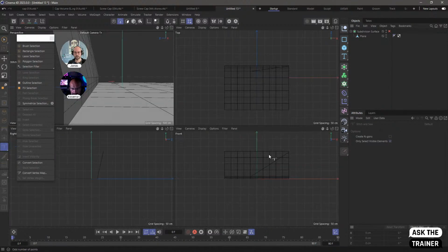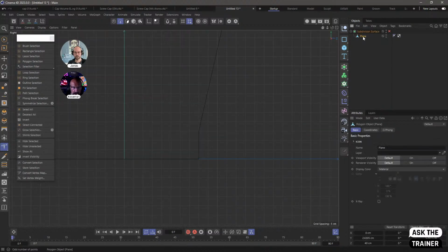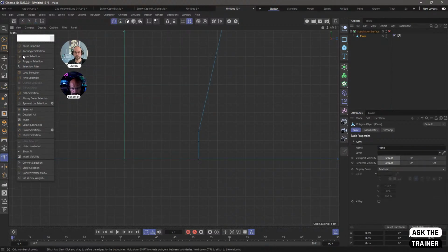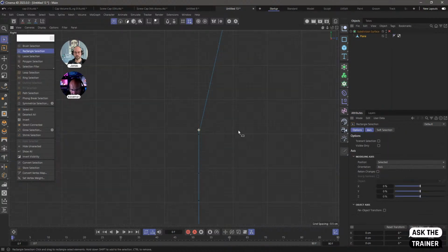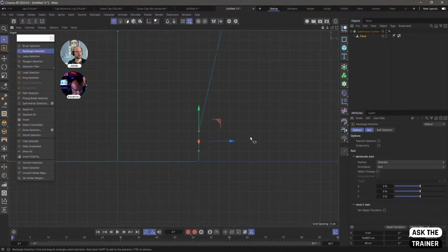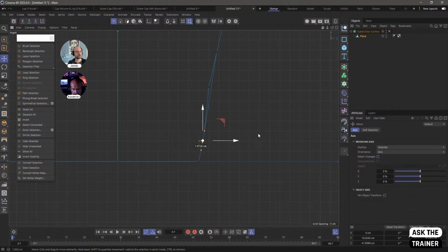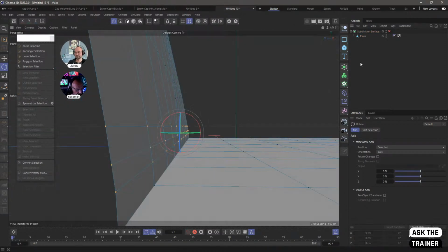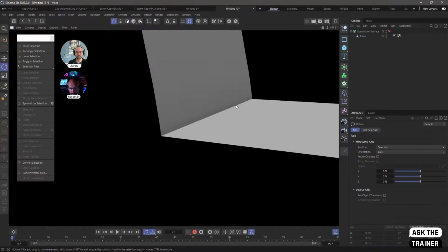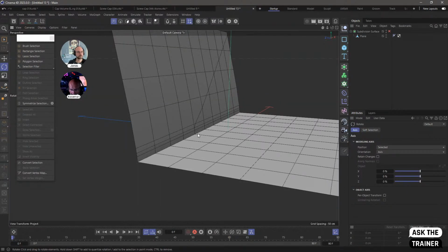Of course, I can go and correct it. Shall I correct it? Yeah. So let's just go and select these. And I should have had these sort of, I can use a straighten tool. I should have done something like this anyway. I'm not going to do it now, bad planning, and I'm not going to backtrack. But as long as this is a straight line, this would have worked. I'm going to get a small artifact up there, but I don't really care now. And generally, keep the transitions that bend with your subdivision surfaces to have all quads like this, so you don't get those weird artifacts. Done.